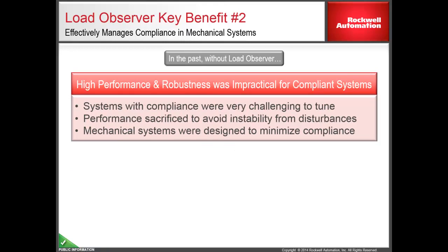In addition, a consistent configuration can be utilized not only across axes, but also across machines. Load Observer also effectively manages compliance in mechanical systems. In the past, prior to Load Observer, systems with compliance were often very challenging to tune. In many cases, performance was sacrificed in order to avoid unstable behavior due to disturbances during operation.